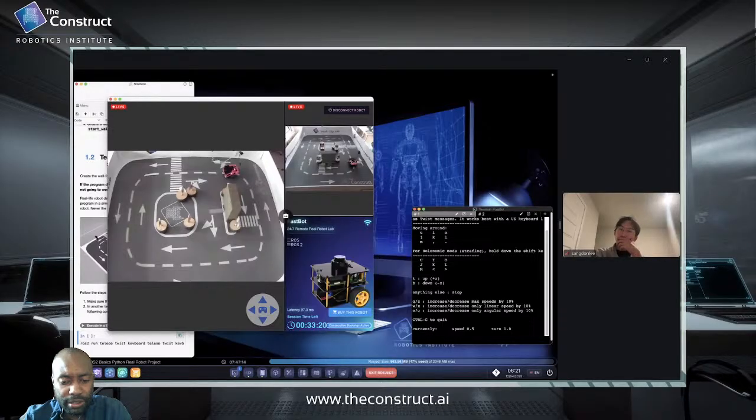Yeah, so at first I was having a hard time making the program work. Instead of using one index value, I tried to give the robot 20 degrees of view for the front part. So I use a range, 10 to 350. I gave a range of indexes so it will have a wider view of the front obstacles. Okay, so which worked best for you in its current state?